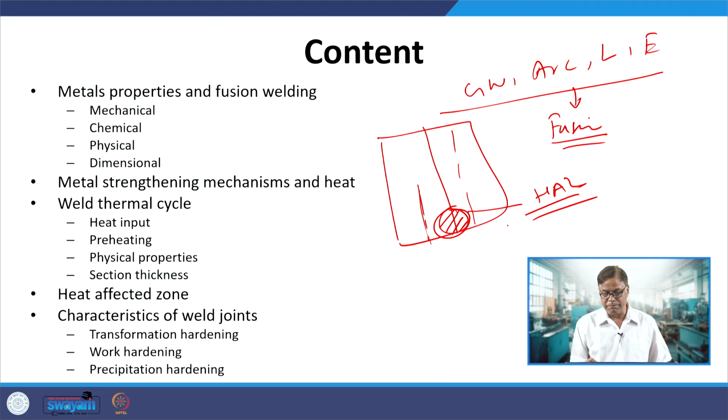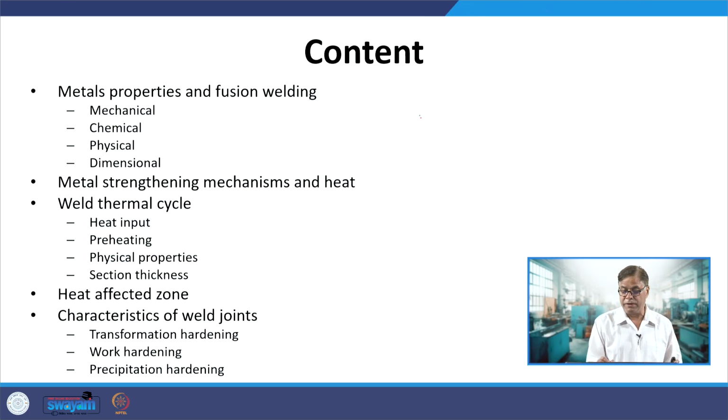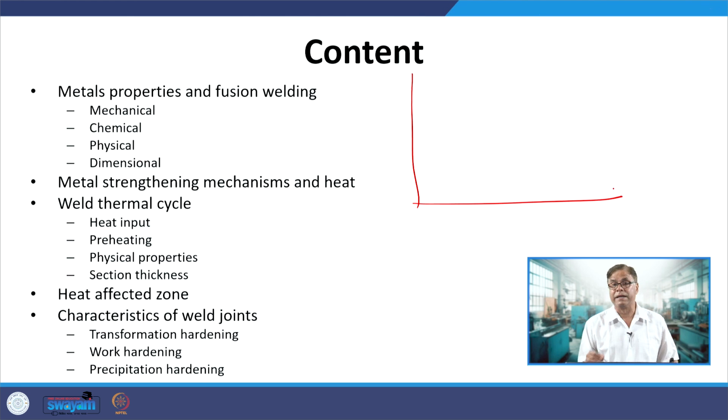Because of the increase in temperature, the structure and properties are affected. So, we say that this is the heat affected zone. That significantly depends on the kind of thermal cycle being experienced. Thermal cycle means the temperature and the time relationship being experienced at a particular point.